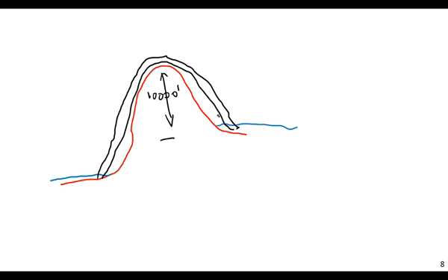But what you might do is have a pumping station down here that pressurizes the system initially and forces the water up the hill. I don't know if you actually could do this, as it would depend on the fluid losses along the walls of the pipe. But if the losses were minimal, you could use this pumping station not to continuously pump the water, but just to get the siphon going. Then you could turn off your pumps and let gravity do all the hard work. You'd only have to expend a lot of energy once to get the siphon going, and then you can let the water flow through the pipe nigh on forever.